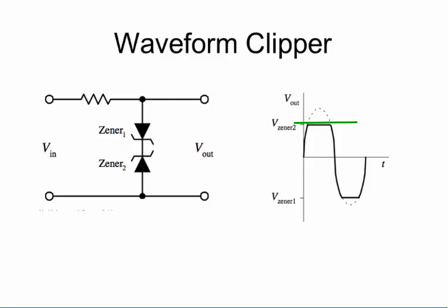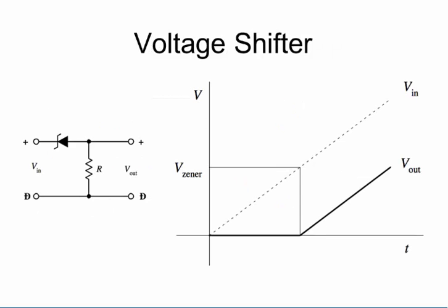As you can see over there, that's the Zener voltage that it would be clipped at. The opposite is also true for the voltage in the negative half cycle. Then the forward and reverse bias are just swapped.